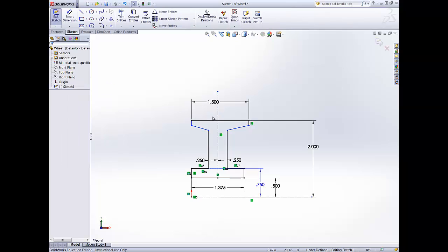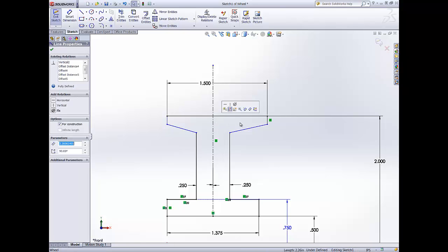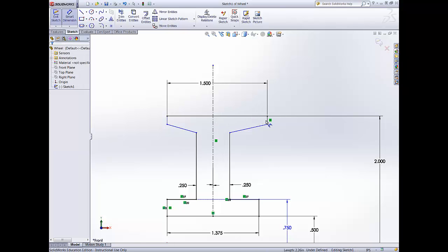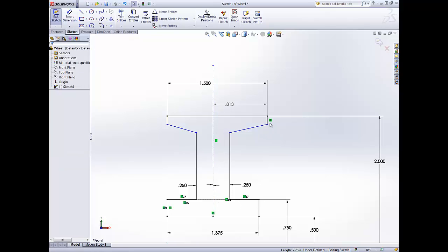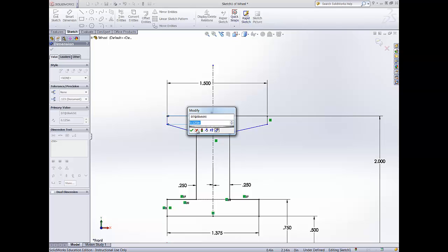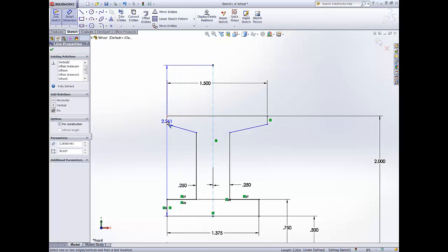Then I'm going to go back into Sketch, because now I'm not constrained as much with it. Do a quick see if I can get these smart dimensions to cooperate with me. So we're holding this one and this one. Not yet. Okay, so what we've got to do is figure out why we're tied down as we are, and it may just be that we need to do a little quick redraw here on that. So let's try to go in the other direction and see if that will give us some flexibility on that. And it seems to be wanting to. It's going the wrong direction. So again, line to line.